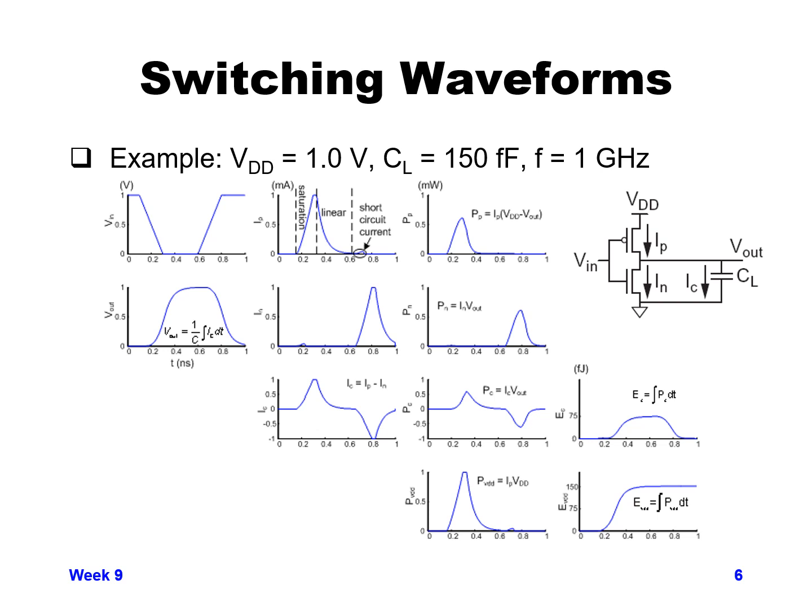You can see the second waveform in the left column, second from the top, is our V out. V out starts low. After V in switches from high to low, V out starts switching from low to high, gets most of the way up to 1, and then V in switches back from low to high, and V out switches back from high to low. The curve has some exponential to it in places, and a linear region in other places, depending on what region of operation we're in.